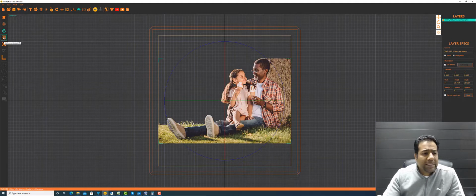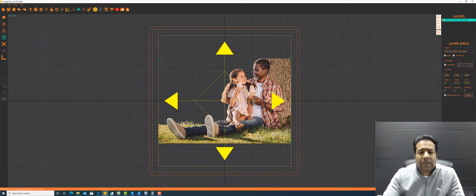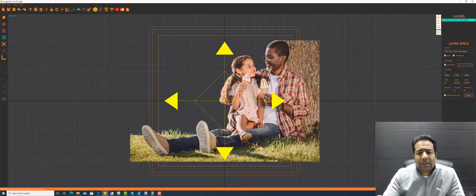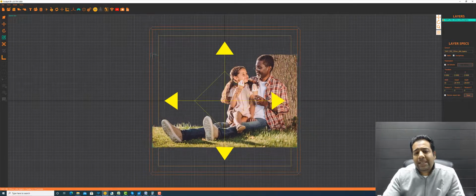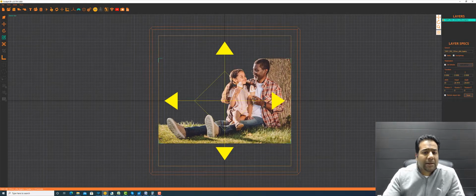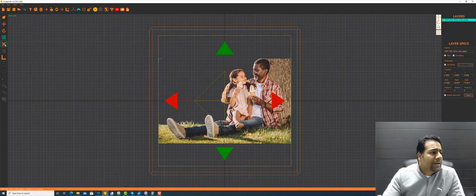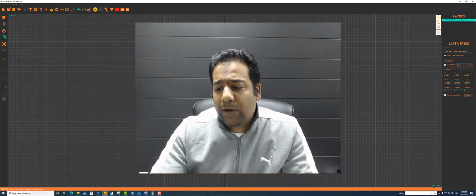If I want to resize the image, I can click on here, and it'll do a uniform. Even the label of it is called the Uniform Scale tool, and it'll allow me to uniformly maintain the scale and change the size of what I'm looking at. This here is the non-uniform scale. So this one here is really good for when you're doing it on the side view.